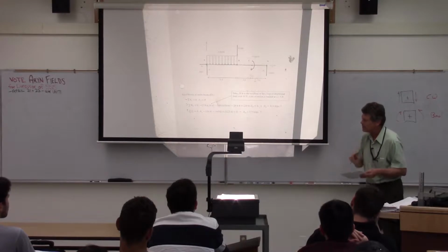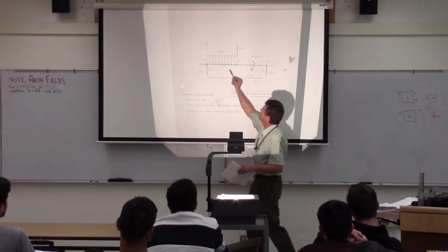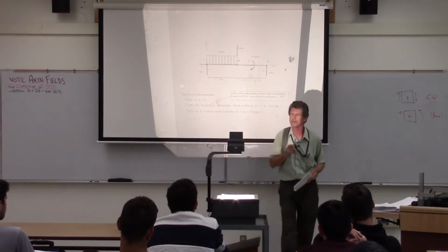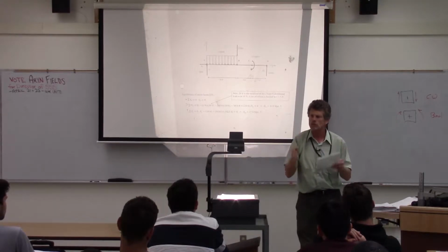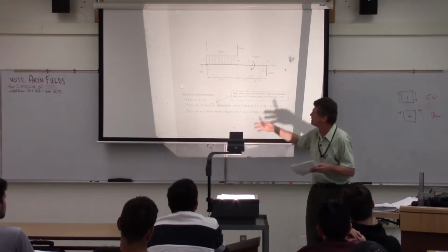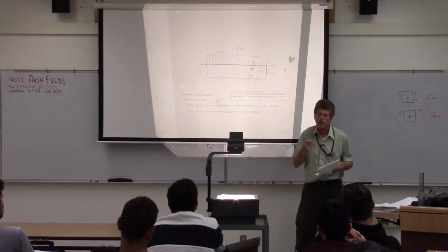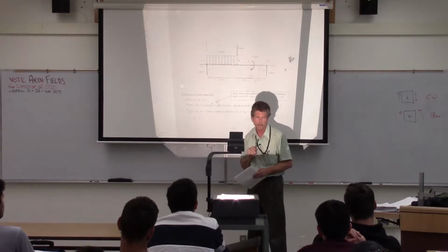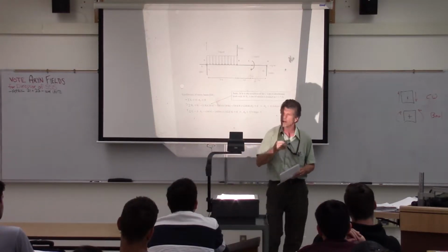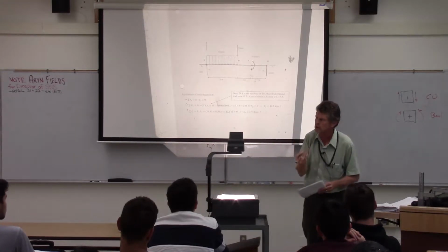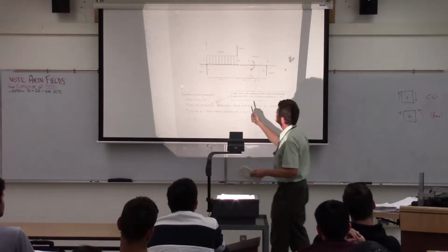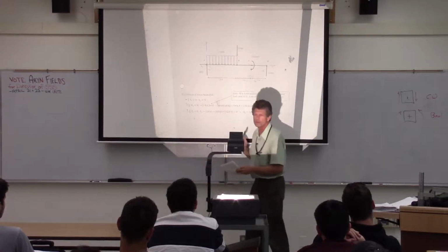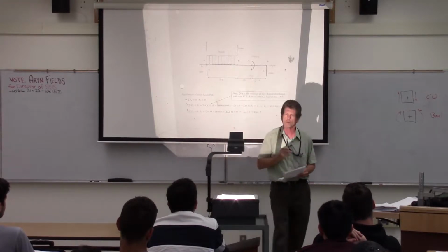Now, one mistake everybody tends to make, and I want you to be careful of: remember when we did this calculation for the support forces, we put in a concentrated load, right? An equivalent load. That's just simply a manifestation, an equivalent load to give us the tools to use our equilibrium equations to solve for the support forces. Our beam does not have a concentrated load there. It's a uniform load. So we create equivalent loads to help us use our calculations, but that is not the load on the beam. And we're going to see that when we look at shear and moment diagrams for areas where there's uniform loads and areas when there's no loads or concentrated loads.